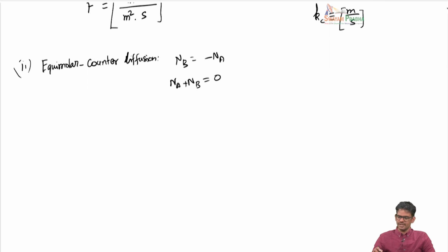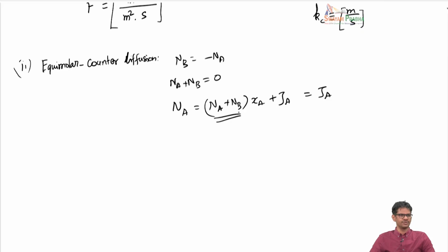So therefore in our fundamental laws of diffusion, this expression simply becomes just Ja, because this term goes to 0 for equimolar counter diffusion.